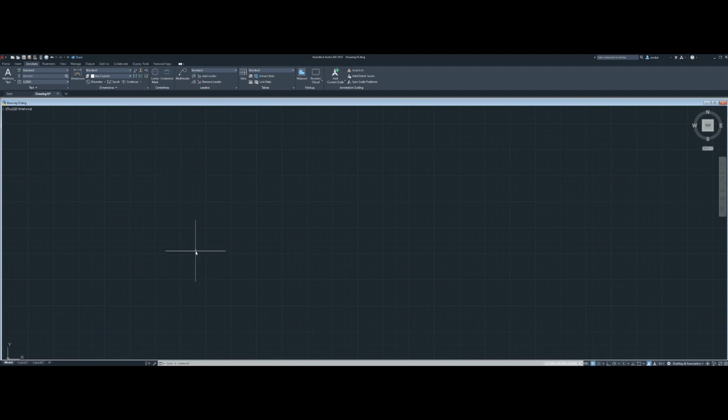To start the drawing, I'm going to create two infinite long lines, one horizontal and one vertical. In AutoCAD, you could create them using the XLINE command by typing it in directly, XLINE, or I'm sure there's a tab, but I'm old school. I like to use commands. I'll enter H for horizontal. I'll just arbitrarily place one here. I'll create another one in the vertical direction.